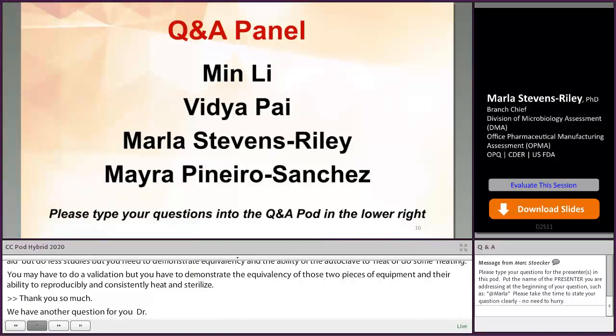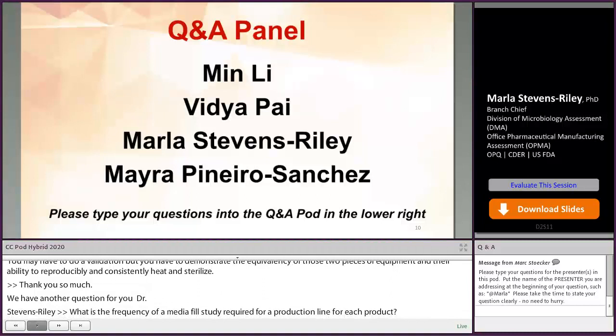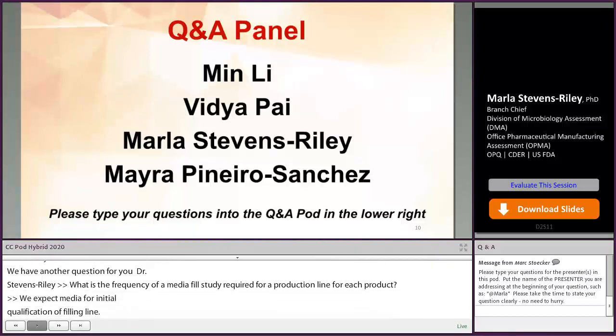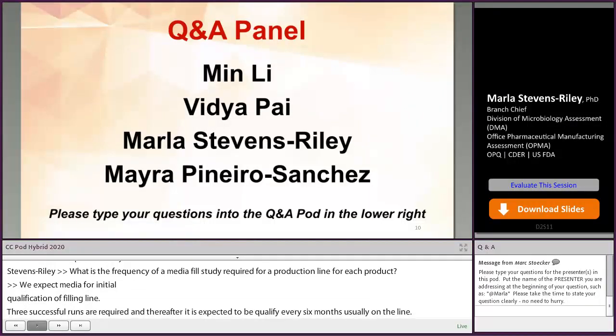So we expect media fills for initial qualification of a filling line, 3 successful runs are required, and thereafter it is expected that you requalify every 6 months, usually on the line. And there is a great aseptic processing guidance that the agency has that describes more of the expectations on media fills and qualifying lines for aseptic processing.